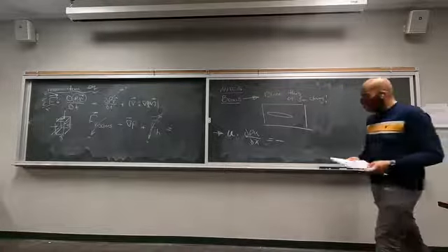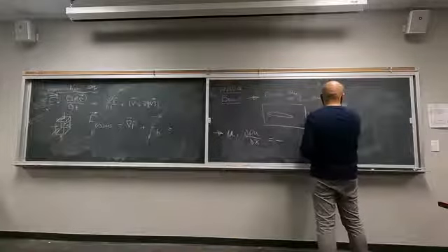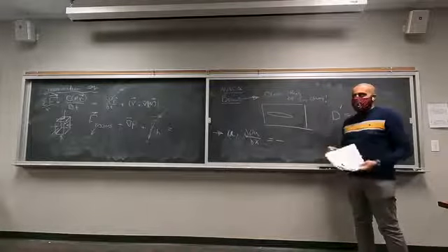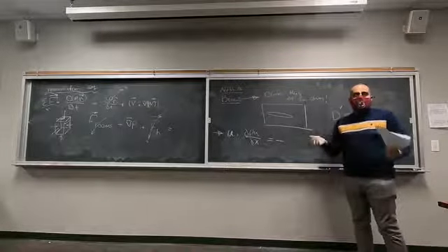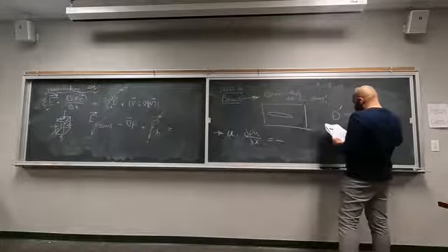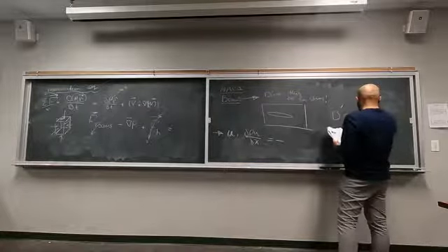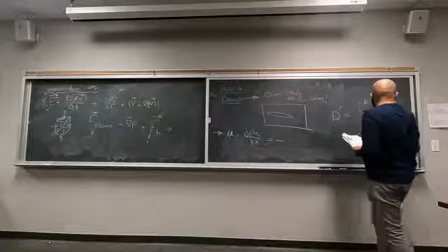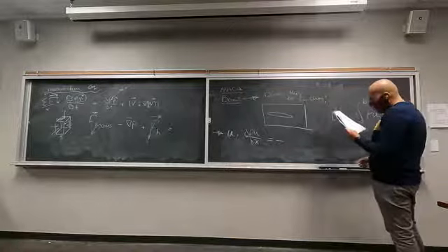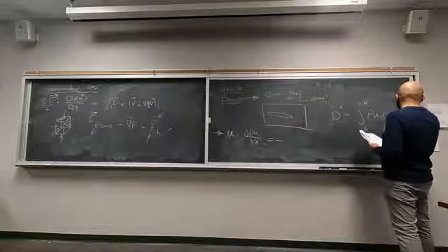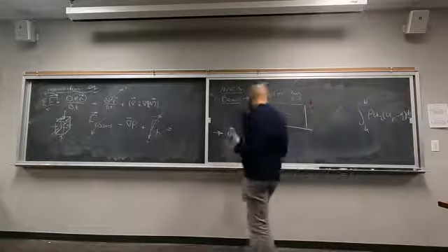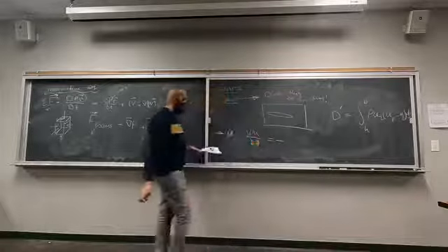And what's going to happen is that your drag per unit length, keep in mind that we have removed the three-dimensional effects. So we are dealing with a two-dimensional drag, which is drag per unit length, is going to be the integral from h to b, rho u2 multiplied by (u1 minus u2) dy. Always make this dy, because you're going to end up with this dy.